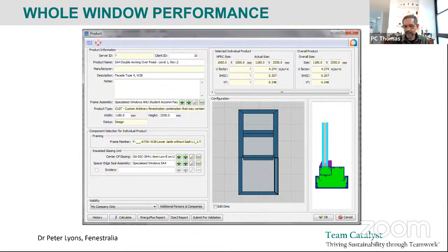You know the solar heat gain coefficient of the glass, and the solar heat gain coefficient of the frame you can kind of assume to be almost zero. It's not, it's a little bit more than zero, but just near zero is okay. And you can take an area weighted average to find what the solar heat gain coefficient is for the system. The U value is a little bit more complicated, but as long as you've got a range that you know you can stick to, then you can make sure that your design is practical.